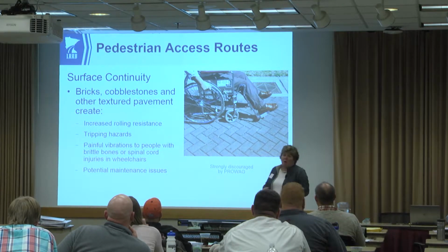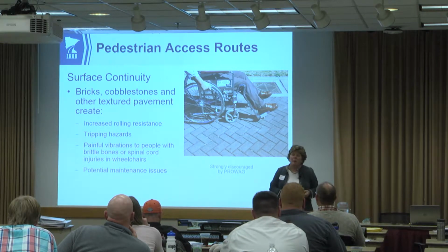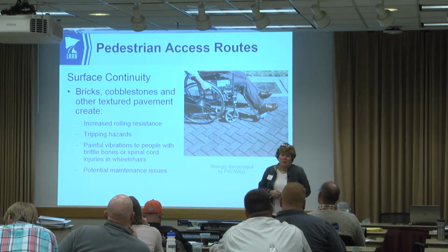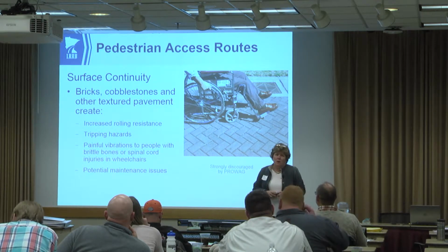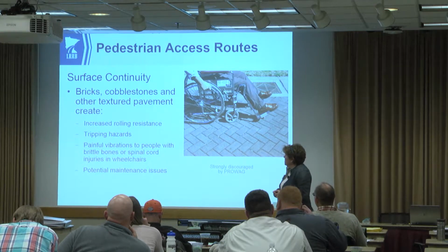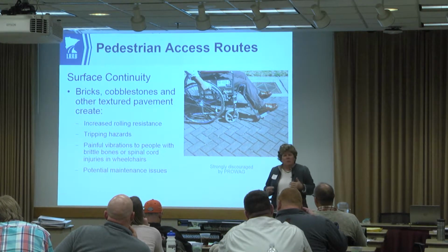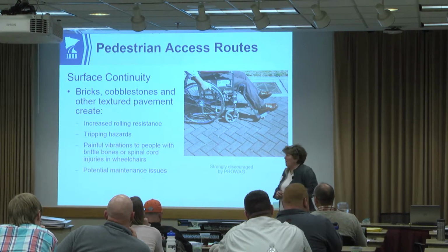We didn't really talk about pavers too much. Some of you have cobblestones, some of you have pavers, remembering that they're a maintenance challenge. If we have 1 or 2 pavers out of tolerance, that can be a real problem for tripping and for water collection. They're painful for people in wheelchairs to go over, especially people with spinal injuries. I've pushed my dad many times over a non-continuous surface, and it's just not attractive.